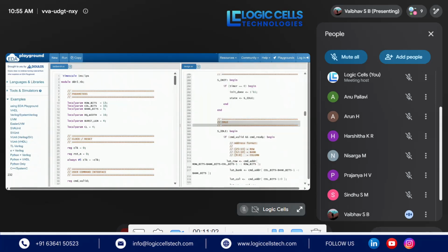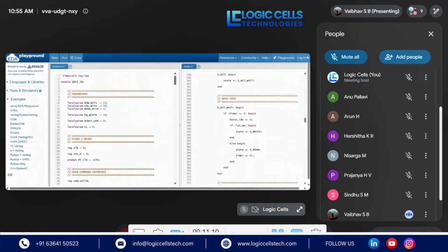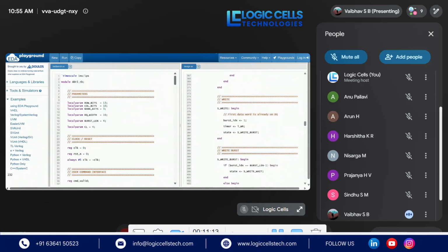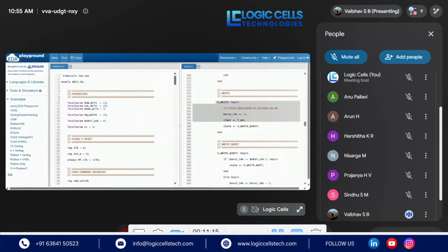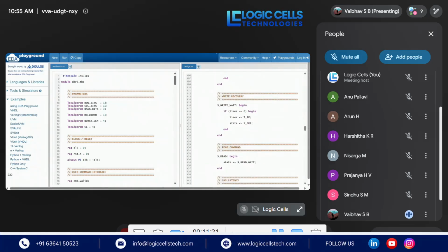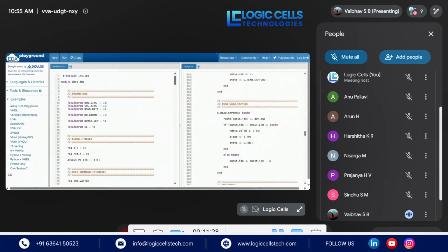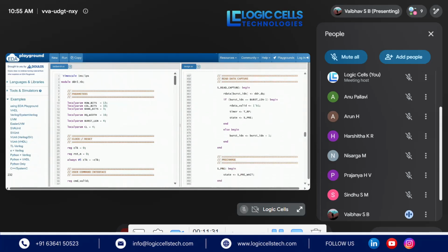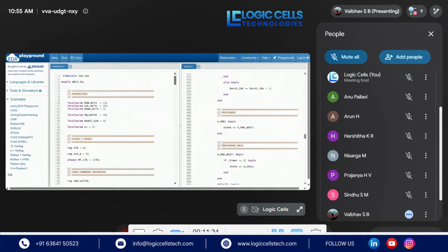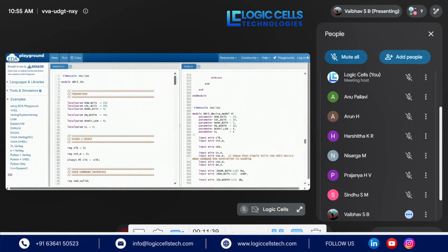Next is the idle state. This is the idle state. Then the activate command, then wait for the row column delay. Then the write happens here, then the write burst, then recovery, a part of the pre-charge, then again the read command, and accordingly the CAS latency, then the read data is captured, then pre-charge, then pre-charge wait, and then comes the model.